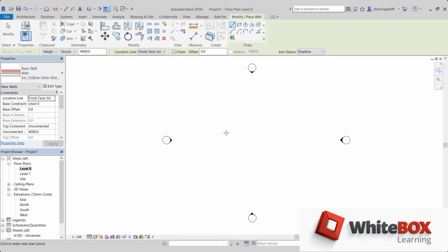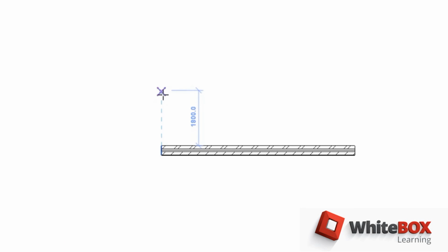When we're modeling a project, we are presented with multiple modeling aids. These aids will appear on almost all of the components which we will use. So if I draw my first wall and draw another wall above it, first thing we'll get is our temporary vertical dimension. You'll see that there's a dashed blue line. That is telling me that that wall, when I start it, will be snapped directly above it. I can also use the temporary dimension to specify the distance before I've even started.